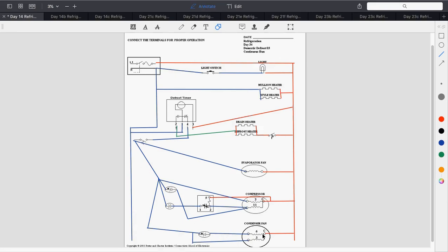Anybody? It's a start capacitor, run capacitor. Run capacitor, but what type of motor configuration? PSC. PSC, that's correct. The capacitor is always in the circuit. We're always giving our start winding some power, but it is slightly out of phase from the run winding because of this capacitor.